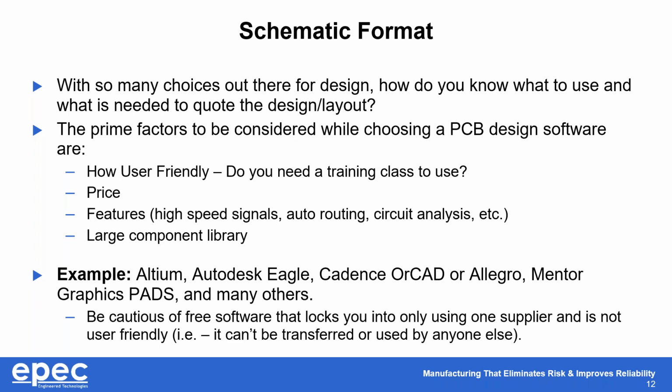The software should include things like high-speed signals, auto routing, circuit analysis, and it should always have a large component library. Some examples of software that are available are Altium, Autodesk, Cadence Allegro, and Mentor Graphics. There are so many out there. If you Google, you'll find a whole bunch, but be careful because some software locks you into using certain suppliers. They do not give you an output format, and they do not allow you to go to the supplier of your choice.